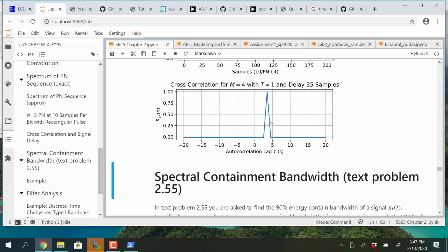This is not a radar application like this example is, but it would be transmitting from A to B. My direct path gets interfered with by an obstruction. A side path gets reflected. They arrive at the receiver, but not at the same time, but you can actually physically combine them with complex weights, and then you can get some of the lost signal back again, which maybe sounds too bizarre, but it's absolutely true.